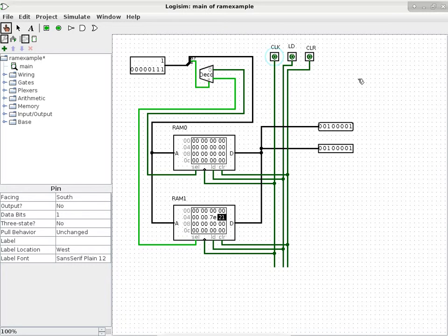Because if the rising edge happens and you are still specifying the data bus, the RAM chip can clock in or store the wrong data because it's not done yet. The data lines are still changing. Are we doing okay so far with that concept? Same thing at the falling edge. Within a certain amount of time before the falling edge, the data line has to change and settle before the falling edge, when the RAM chip is sampling. Okay, are we doing okay so far with that?